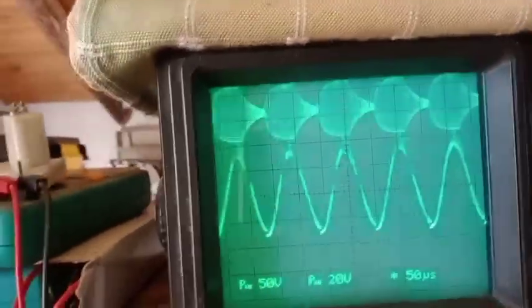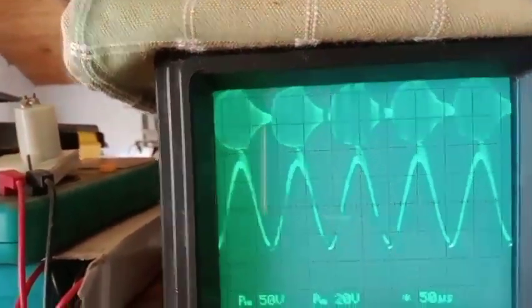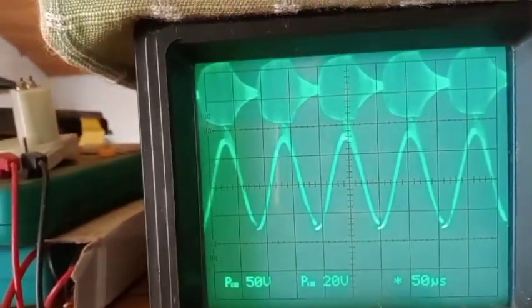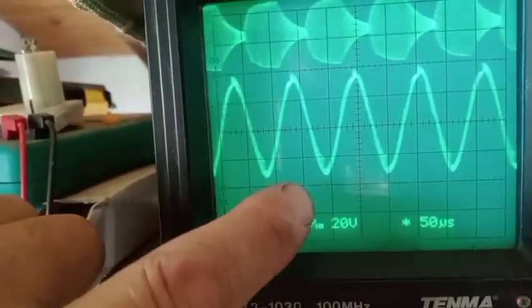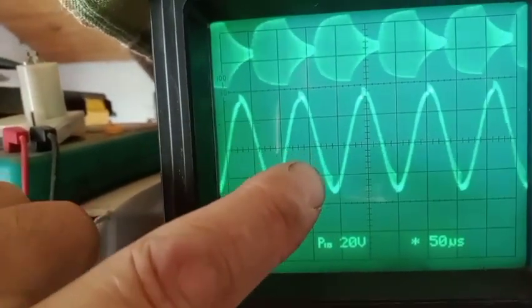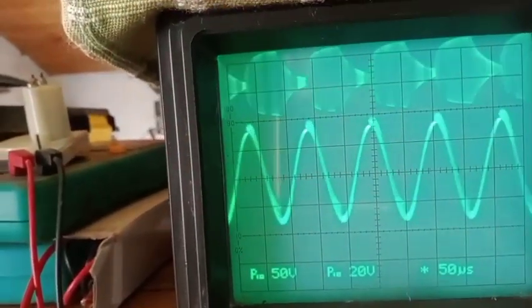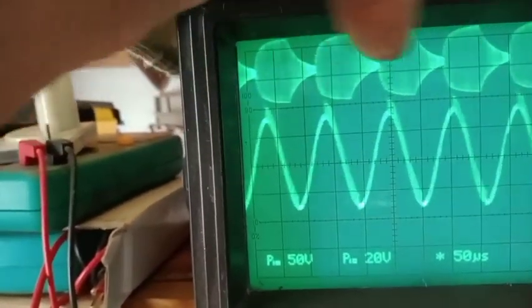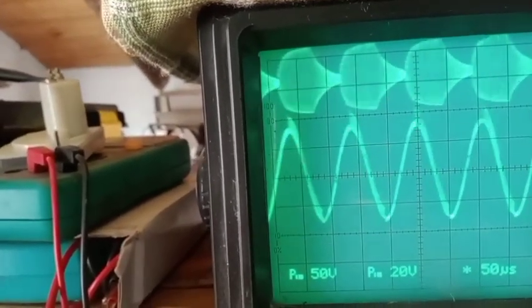My signal generator, which I'm using now, is limited. I cannot reduce the duty cycle because I don't have more channels for this. But if I change the phase angle, you can see how it goes on the negative side in the other direction. So this would be an indication that the driving should be parametric. It should be a quarter of a period, not half of the period like it is right now.